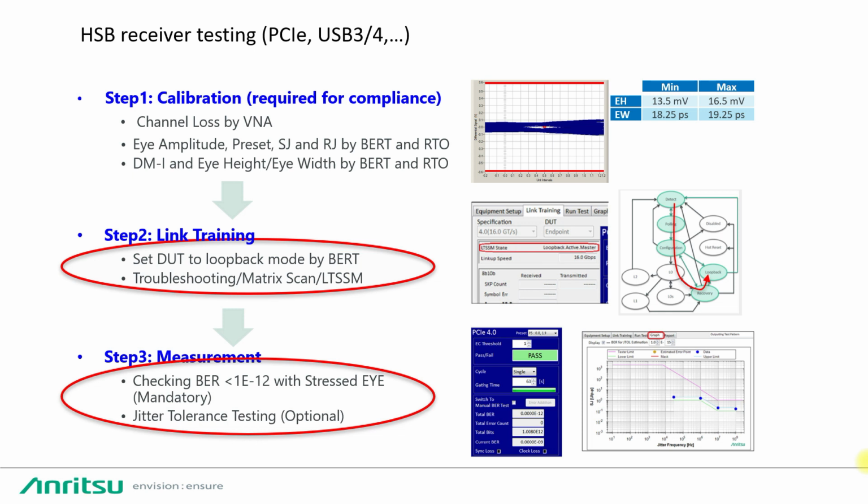DOT. PCI Express and USB Gen 3 and beyond both use link training to establish the optimal transmitter and receiver setups depending on the link quality like loss and jitter and the link partner's properties. Most important, the optimum presets and data rate to be used for data transmission are negotiated during the link training. In case link partners are of different generations, the lower data rate is being used.